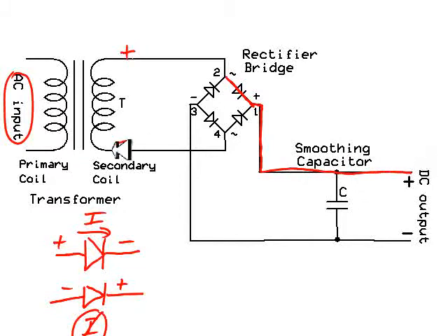The negative wire of the transformer is connected to these two diodes, but this one is going to be off. This one will be on. And so it's like a closed switch. So the negative voltage will then appear there. So these two diodes are on, and the other two diodes are off.